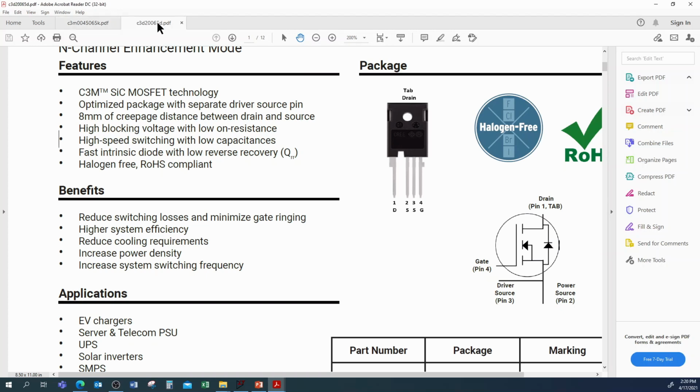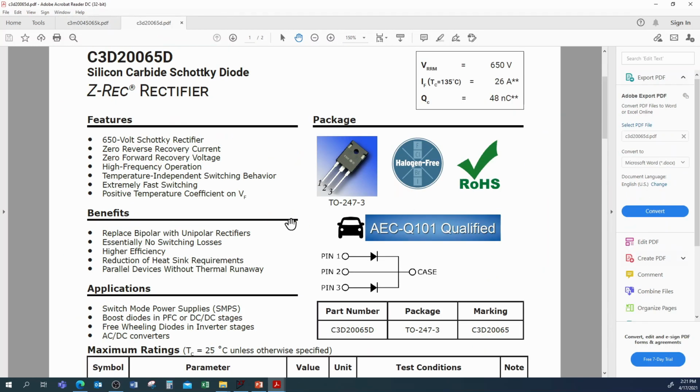For our flyback, because we have an inductive load, we want to put a flyback diode in there, and we are going to use this diode, which I pre-selected. Notice it's actually 2 diodes that we are going to use in parallel. We have the anode for diode 1 on pin 1, the anode for diode 2 on pin 3, and the case and pin 2 are connected as well. So we'll be utilizing this device in our circuit.